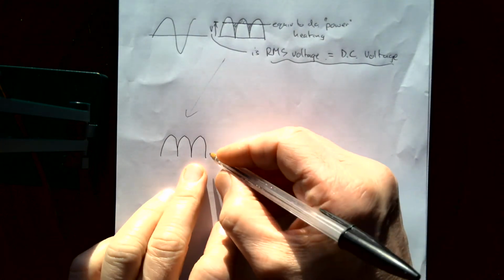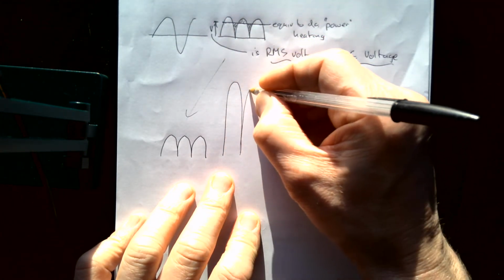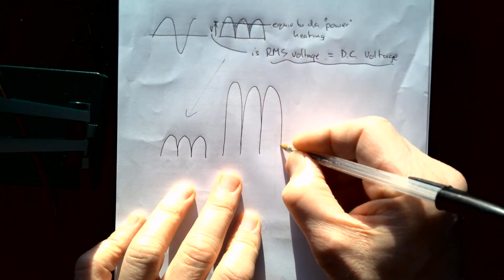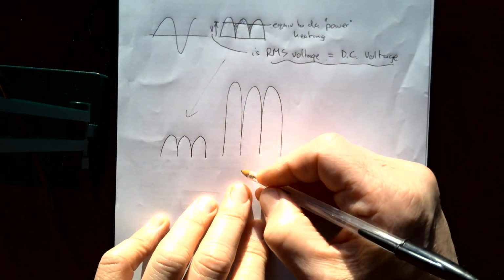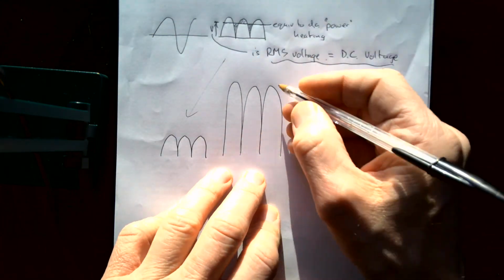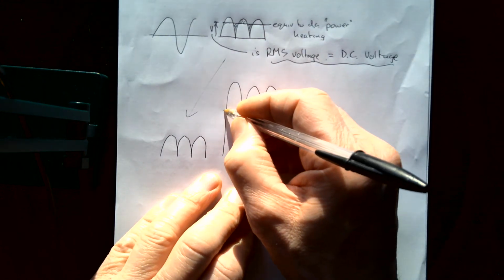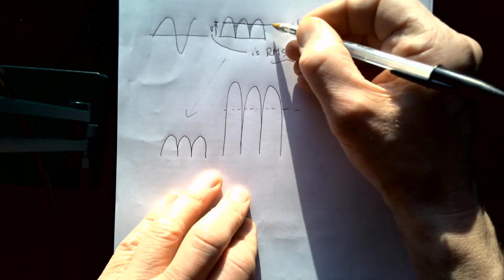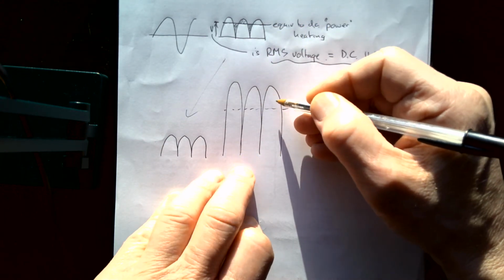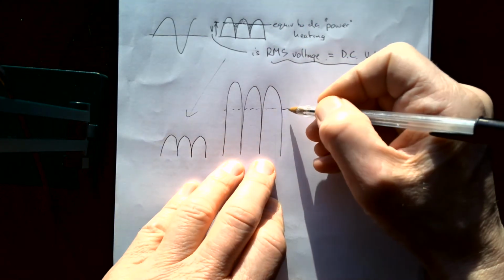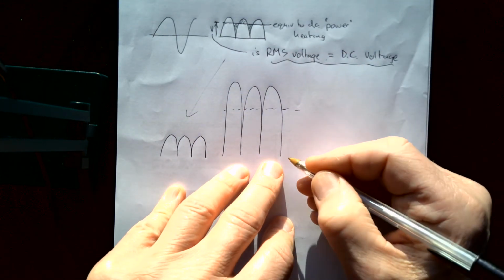So what we're going to do is we're going to square it. So we're going to go to much higher. Apologise if actually you've done it wrong. It should be that one. But again, much higher. If we find the mean of that, okay, the mean value as it fluctuates, you'll get a certain value. So it will just be like this. Unfortunately, it's now twice as big, or not twice as big, it's the square of that value. So if you then square root it, it turns it back again.